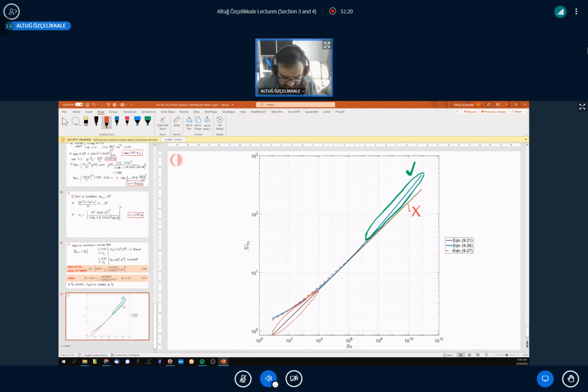That's because when you have flow velocities decreasing, then the conduction within the axis of the flow, meaning in the streamwise direction, the x direction, becomes significant. When we were deriving these boundary layer equations, we assumed that the dominant mode of heat transfer across the flow would be by advection.